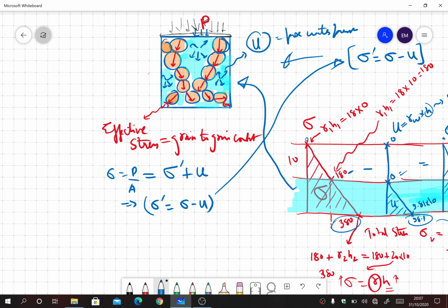Just to jog your memories, we studied in Terzaghi's one-dimensional consolidation theory that if we imagine in the same figure that this hole is really closed and there is no way for water to escape and no chance for volume change, you can imagine this is a steel box and this is the piston that is fixed. Once I apply all the load, all the load will result in increase in pore water pressure. There will be no grain to grain contact load transfer in the soil specimen.